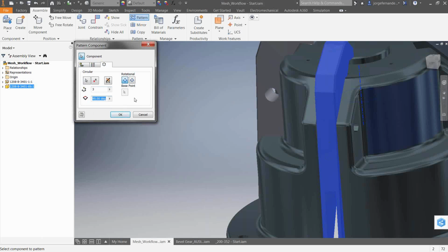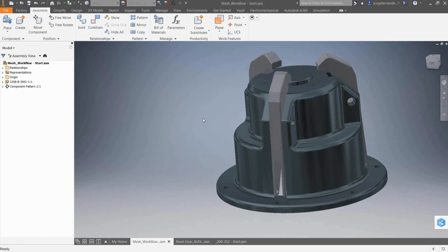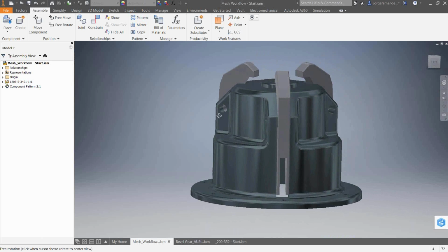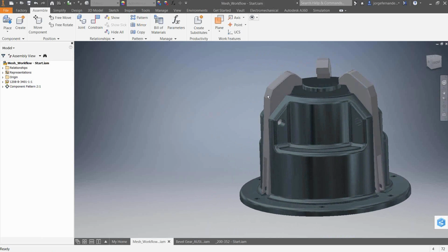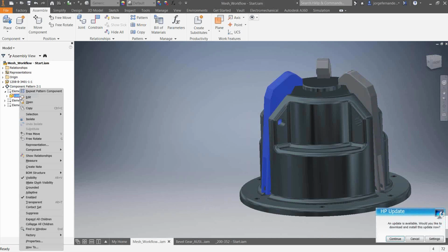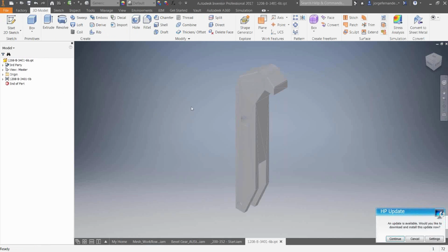And by simply using this feature to not translate and import, but reference to it, it's definitely going to save you in terms of performance and file size. So something to keep in mind and definitely start using instead of an import, unless you need to actually change the geometry.